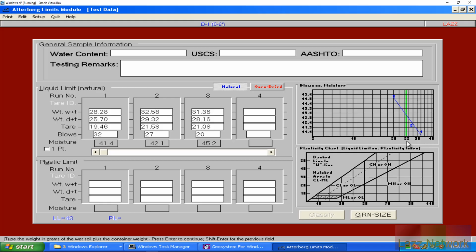As you can see down here, this is your number of blows. So you have your number of blows down here, and this here is your actual moisture content. Your number of blows, at least for your table, always stays in the same orientation. That almost never changes on your table. It's usually your moisture content. Moisture contents can vary from material to material, okay?